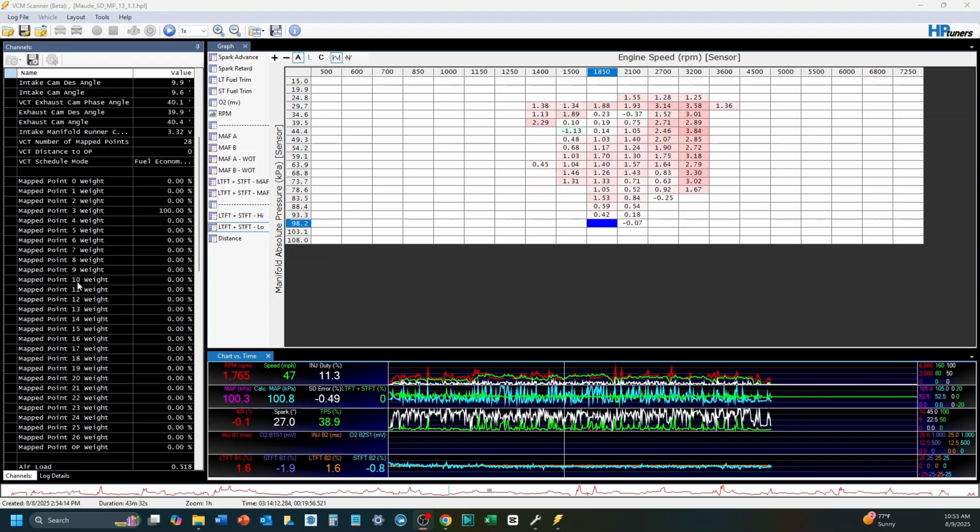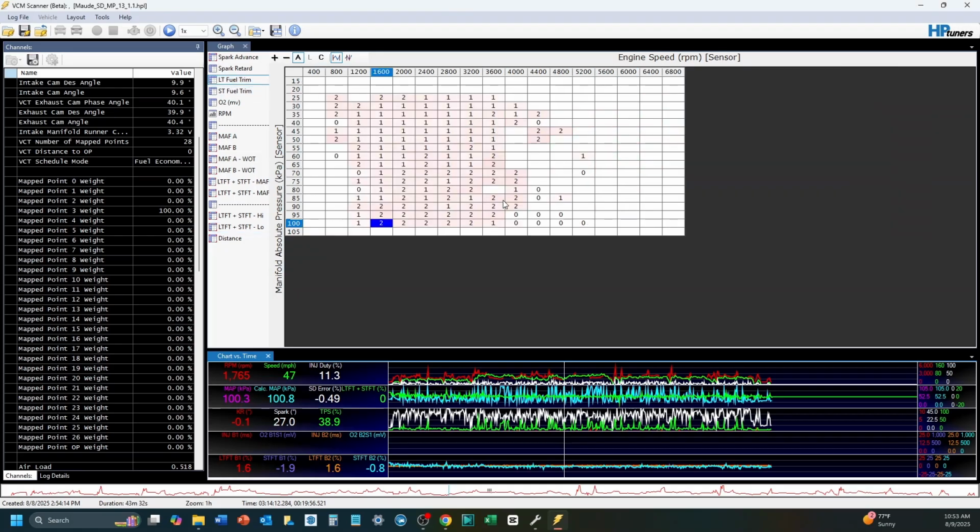And when you look at the logs, you start to get this lovely map. And so a couple of things here. You can see my long-term fuel trims across the board in this iteration. Little lean, nothing major. They're joined by the ST fuel trims, and we're seeing as well they're pretty much within range. I'm not seeing wild, big, crazy corrections. That's what I want to see.